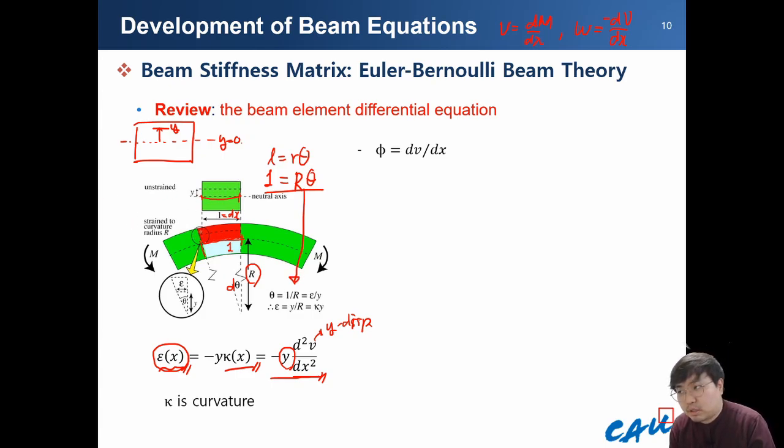And also in this part, I obtained the deformed image here. I defined this length as y, and this part will be increased, which I indicated as epsilon. From the triangle relationship, or similarly the arc length relationship, the total strain is equal to theta r over y, so we obtain the same relationship here.